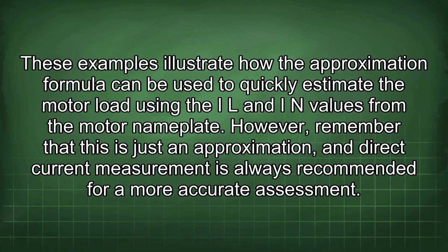These examples illustrate how the approximation formula can be used to quickly estimate the motor load using the IL and IN values from the motor nameplate. However, remember that this is just an approximation, and direct current measurement is always recommended for more accurate assessment.